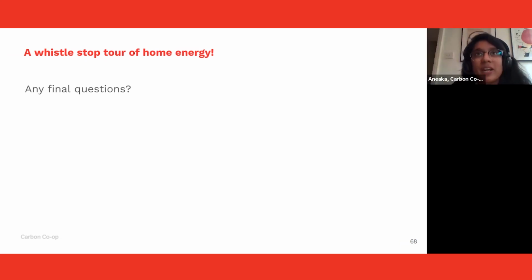I don't know lots about that, but I can imagine if it's a top floor flat in a building with lots of suspended timber floors, rather than a concrete flat, there might be lots of air movement coming up from downstairs. So in terms of indoor air quality and health, if the people downstairs are smokers, you might smell smoke, or if they don't ventilate their flats properly, you might get lots of their warm and moist air in your flat. I guess the main thing to do would have been to monitor your situation, check what the relative humidity is and then deal with it yourself.